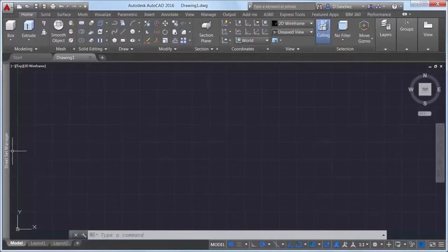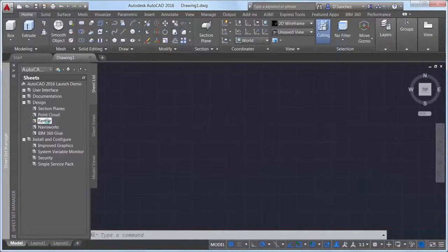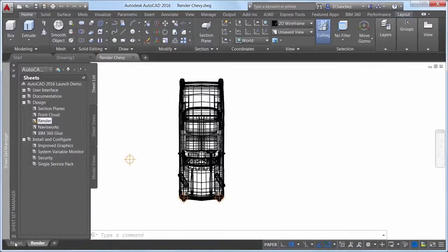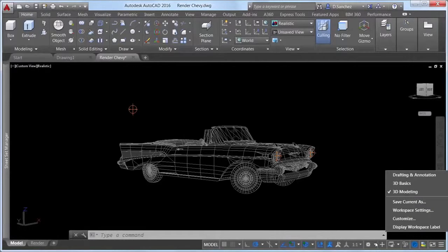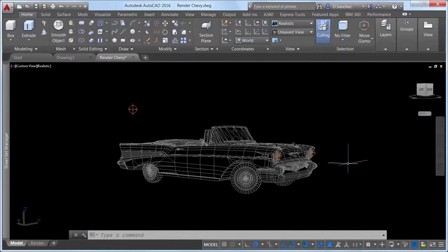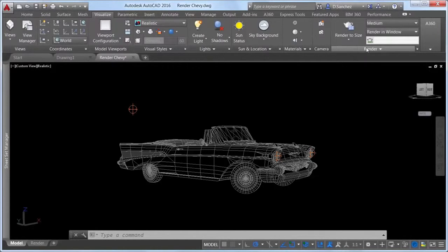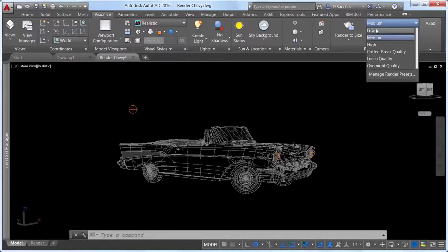The new rendering engine in AutoCAD 2016 replaces the previous one. This physically based path tracing renderer provides a simpler way to render in AutoCAD that can produce better results. The new Render UI has significantly fewer settings, making it faster and easier to create renderings. Render presets enable you to specify the render quality either by the number of rendering iterations or by how much time you want to allow it to render. Tooltips assist you in making an appropriate choice.